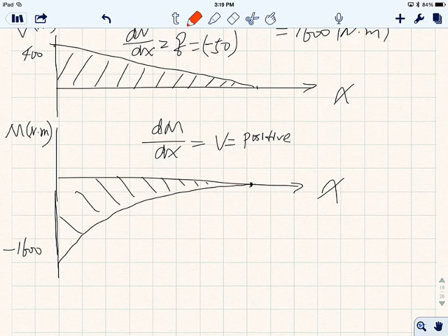Okay, but by saying that, it doesn't mean in the future when you are taking a quiz or exam, if you have a positive over here going down to 0, I'm going to deduct some points from you. No, why not? Which I'll tell you later, because you can just see from the figure, right? So in other words, if you have a bending moment diagram starting from 1600 and then going down to 0, it's okay too, right? Because all we care about is the absolute number over here, okay?